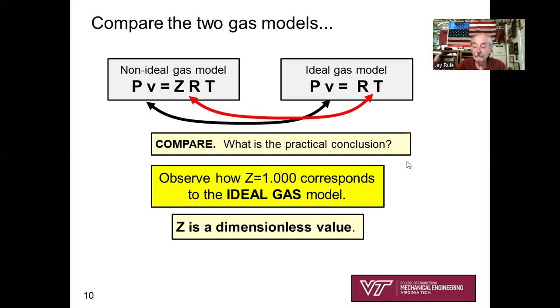It would be 25 degrees inside that tank, and it might only be 100 psi. Gosh, I can't, off the top of my head, think of what that is in kPa. It might be 6 atmospheres. Well, 600 kPa then, right? So you will find that Z is 1.00 for the compressed air in the compressed air tank as well.